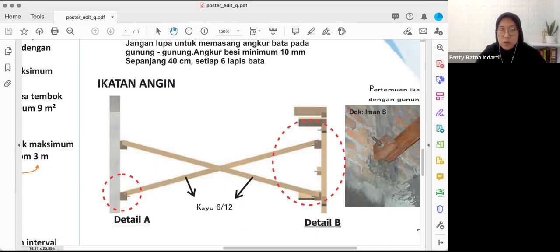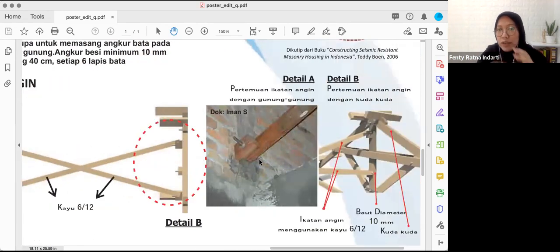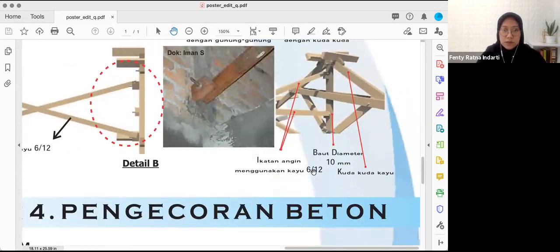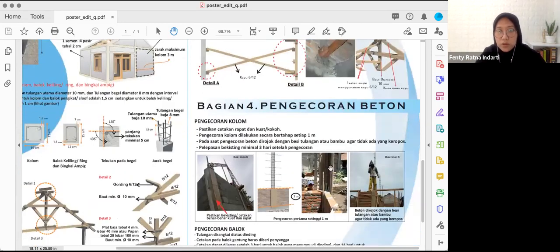So this is what the purlin looks like, and this is how the purlin's connection looks like. It has something attached to this part. It is sunken, planted on the wall like this, with concrete for the reinforcement, and then it is protruding like this, and then attached with another wood to create the purlin. So those are the purlin, and that's it. And then you have those types of patterns on top, and cover it with the roof covering.